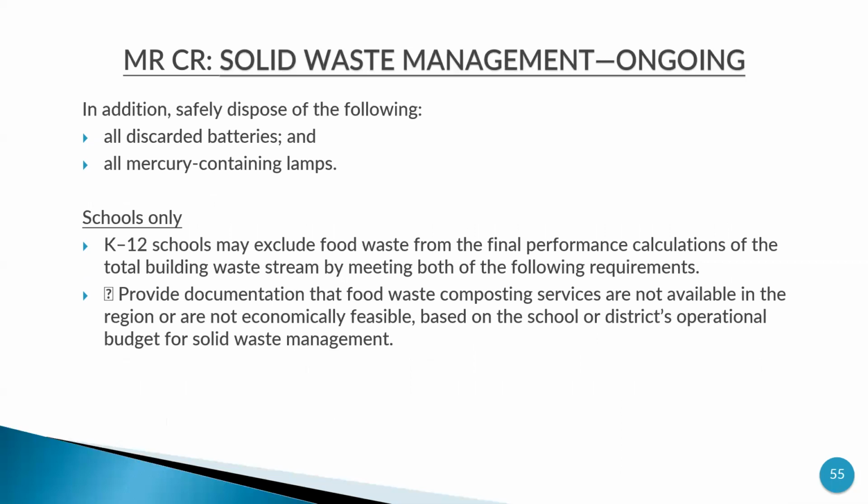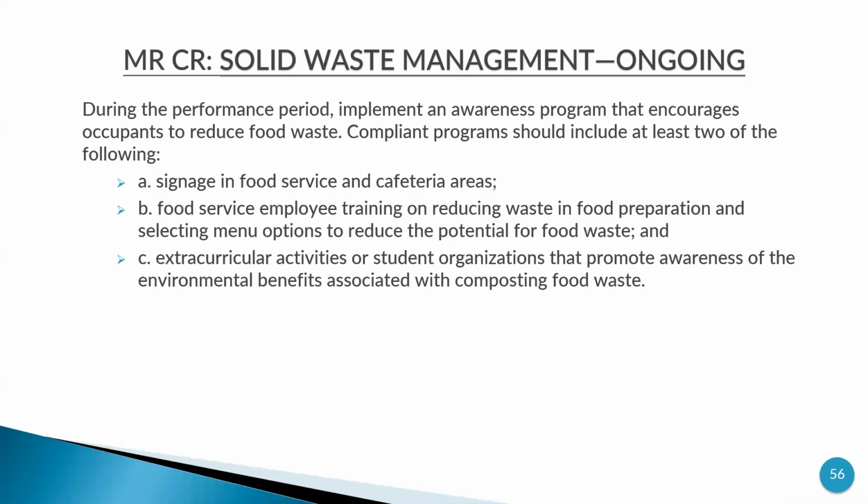Yeah. Again, in addition, safely dispose of discarded batteries and mercury-containing lamps. These two things. Then coming to schools, from KG to 12 schools, exclude food waste from the final performance calculation. See here, food waste is excluded from the final calculations of the total building waste stream if food waste composting services are not available in the region or not economically feasible based on the school or district operation budget for solid waste management.